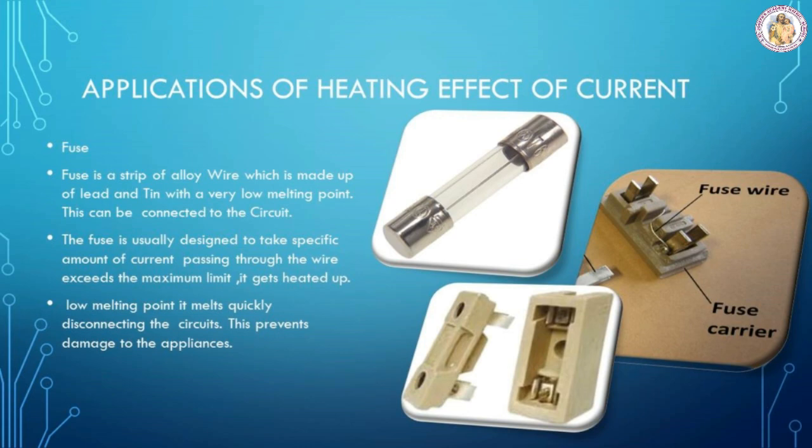Application of heating effect of current. First, fuse. A fuse is a strip of alloy wire made up of lead and tin with a very low melting point. This can be connected to the circuit. The fuse is usually designed to take a specific amount of current. When current passing through the wire exceeds the maximum limit, it gets heated up. Due to the low melting point, it melts quickly, disconnecting the circuit. This prevents damage to the appliances.